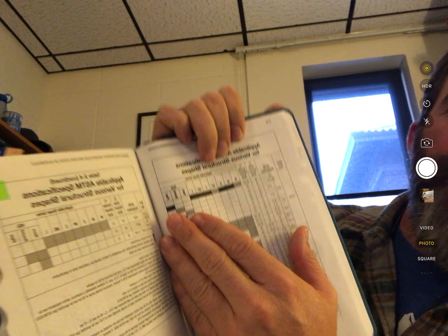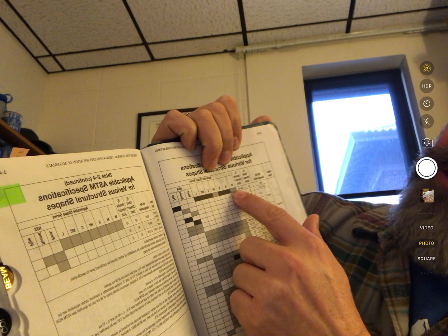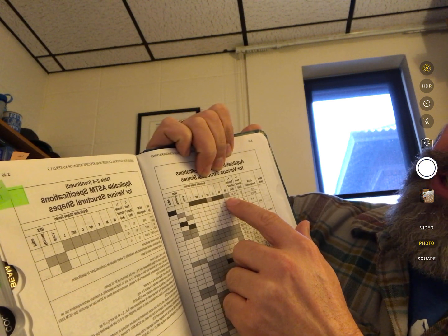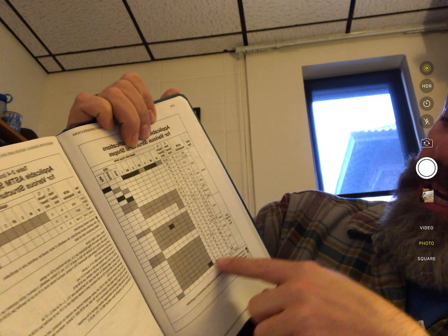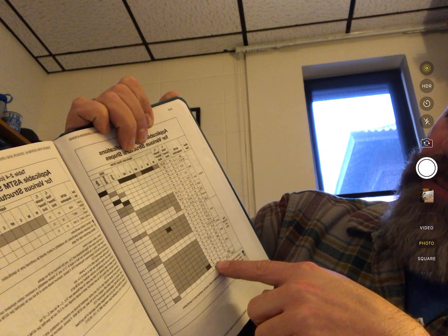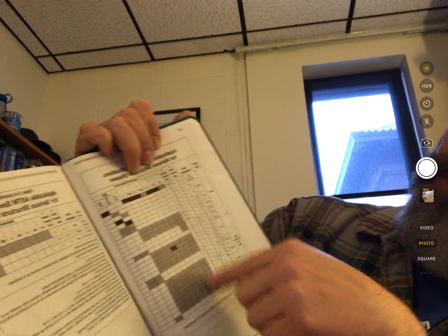They have different grades of steel as you go down this column right here, and it's worth discussing for a little bit. If here's a wide flange section, it tells you what the typical type of steel a wide flange section is made out of. The black right here indicates the standard steel, and it's made out of A992 grade 50 steel down here. And then here are all the different types of steel you can get it in. If it's tan, you can get it in any one of these types of steel. These are all different types of steel going up and down. But they also tell you what's the standard steel that it's made out of.